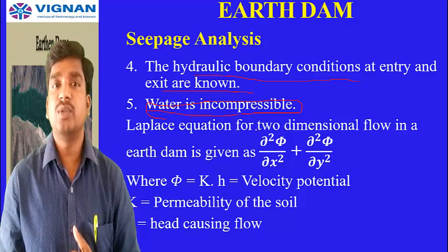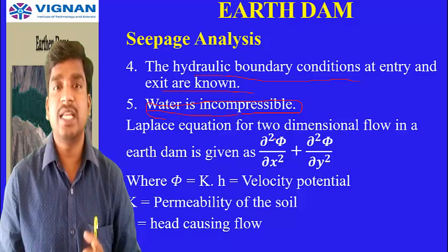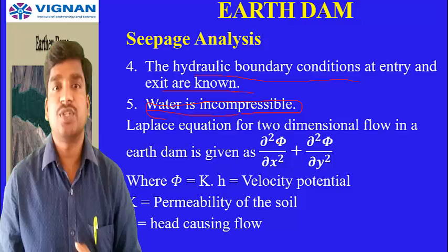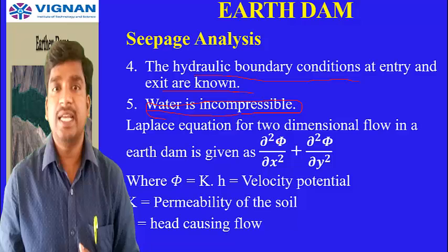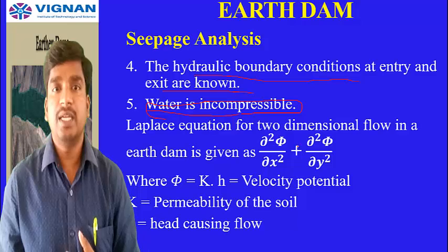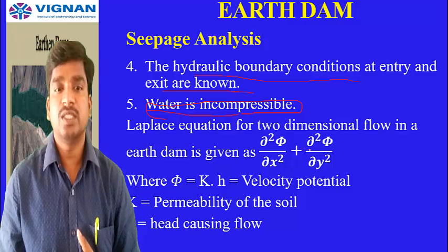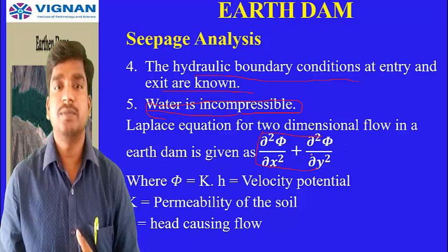Okay. So now let us get into the seepage analysis procedure. In the seepage analysis, we will take the help of the Laplace equation for two-dimensional flow, right? To calculate the seepage in an earth dam, we will take the help of the Laplace equation for two-dimensional flow in an earth dam. That is given as ∂²φ/∂x² + ∂²φ/∂y² = 0. This is the general equation for two-dimensional flow of fluid.